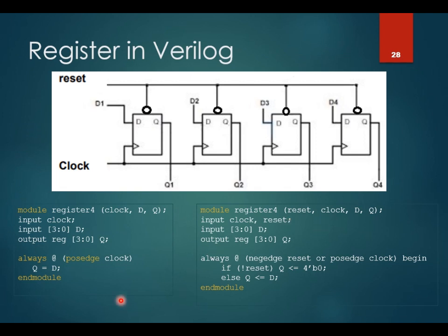We can expand how we describe a D flip-flop to a multiple-bit register. Say you want to describe a 4-bit register. A 4-bit register just consists of 4 flip-flops separately, but they share the common signals like the clock signal and reset signal. Each of them still has its own input like D1, and own output Q1.